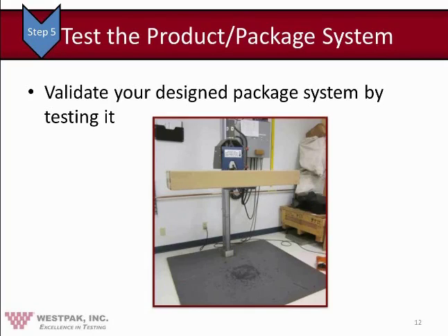And during vibration testing, you're trying to validate that at the product's resonant frequency, you're actually in attenuation, which means that your amplification that was originally 10x might now be 1x. Same thing for temperature, humidity, and pressure differentials. With altitude, you're just validating that your package works in these conditions. And at the end of the day, if the job was done correctly, an optimum package system now exists for this product.